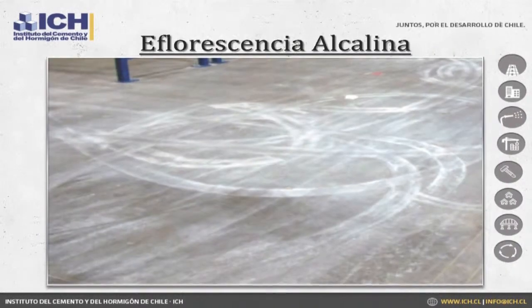Another problem, a pretty significant one, is efflorescence. It's salt deposits on top of the concrete. As the water evaporates into the building, it brings all these high alkalinity salts to the surface of the concrete that end up just sitting there. This is a problem because it's dangerous, for one. It's extremely slippery, so if you're driving forklifts on top of efflorescence, your forklift will not be able to brake, and I've seen them slide 20 feet when they try to brake.